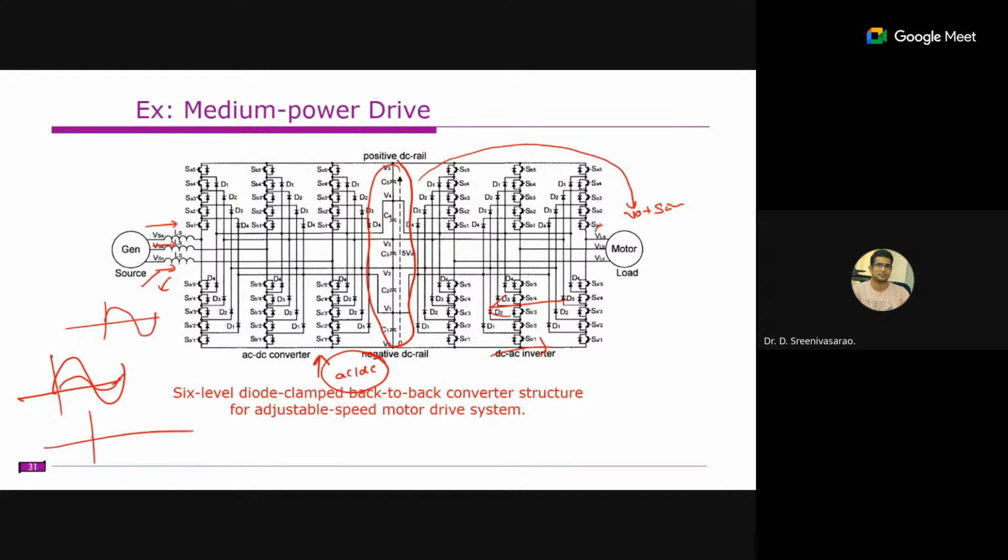If it is reverse power, we have it like this: this is the voltage and this will be the current. Every time it will draw sinusoidal current in phase with the voltage waveform. If you require some reactive power, we can also deliver the reactive power. Those things the other resource person will discuss when he is discussing the current control methods like decoupled control methods. Thanks, sir.